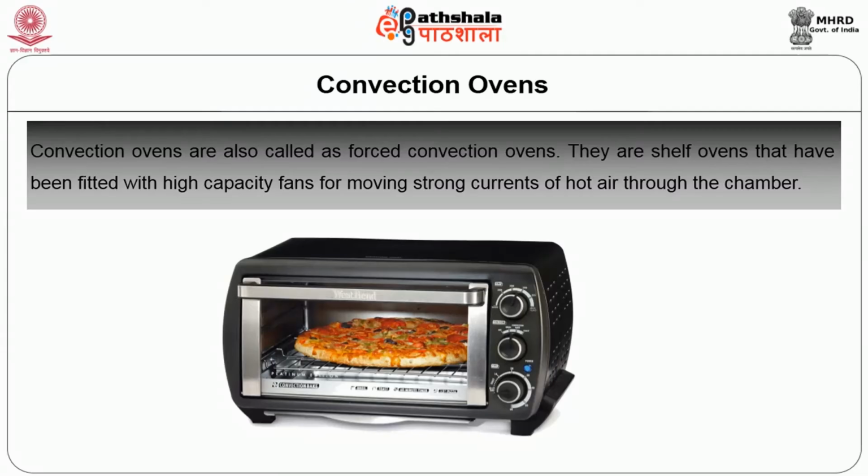The oven is furnished with 2 of these carriages so that one can be loaded or unloaded while the other is baking. The surface area of the 28 trays is about 50 square feet. A window in the door of the oven allows constant inspection of the interior. 2 reversible centrifugal turbines driven by 2 HP motors provide the convection air. An automatic programmer or timer can be used to reverse the operating direction of the turbines so that uniformity of heat distribution can be increased.